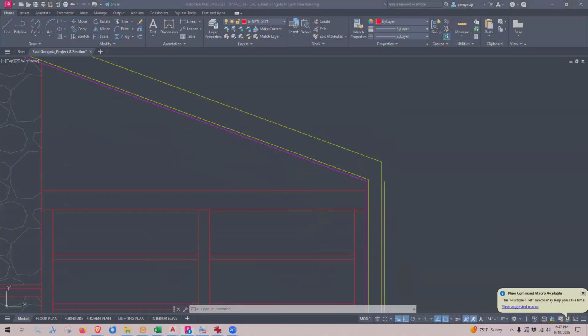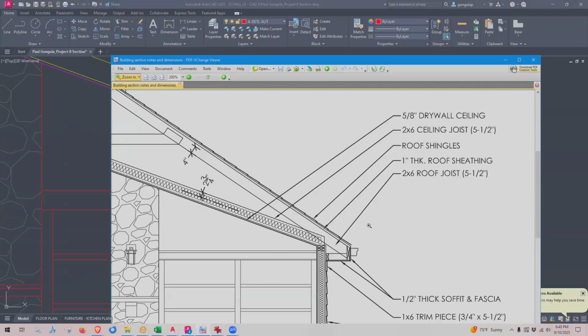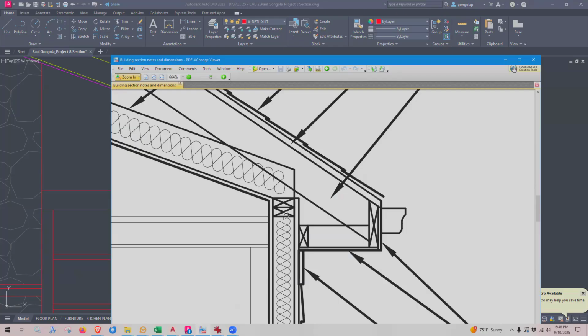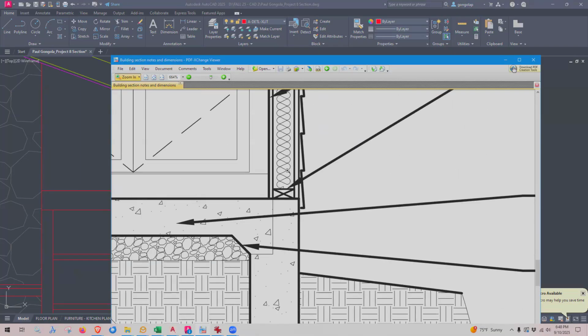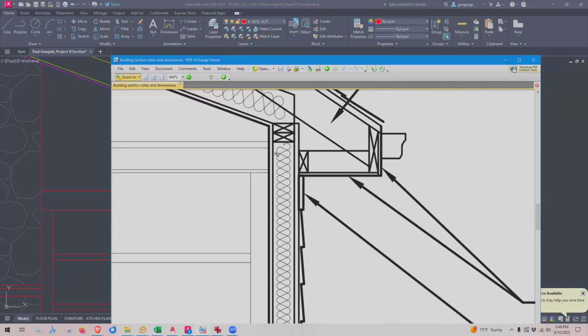Okay. So now at the top of my wood studs, I have two of these studs in section, just like we drew for our sill plate, and they are right up here. And these two studs are called a top plate. Sill plate, one stud; top plate, two studs.